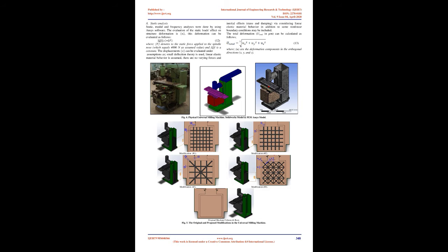Results and discussion. The two softwares were built and tested for calculating the cutting forces and required power for the milling machine. The results obtained from the software were compared with those obtained from manual calculations by using the calculator and nomograms given in textbooks. Many cases of cutting conditions were investigated. Table 1 presents the power and cutting force estimated by manual nomogram, hard copy, nomogram software, VB, and equation software, VB, for steel alloy, carbon steel, light alloy.